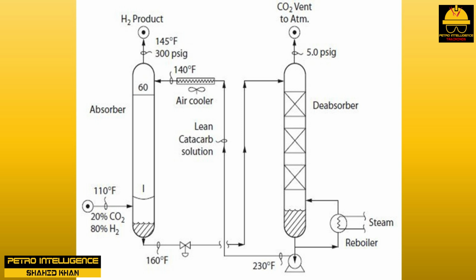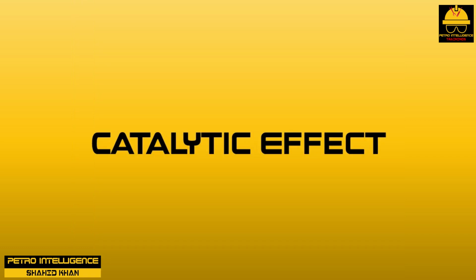Waiting for the main course, he thought about the problem. Why would raising the absorber temperature, clearly bad for equilibrium, reduce CO2 in hydrogen? Certainly, absorption efficiency is improving, not because of equilibrium, but because of kinetics. It must be reaction rate or time limited. Otherwise, the higher temperatures in the absorber would never help. "Mr. American," he asked, "what about the LRS-10 catalyst? Has it cleared customs in Klaipėda yet, the old German port of Memel?"